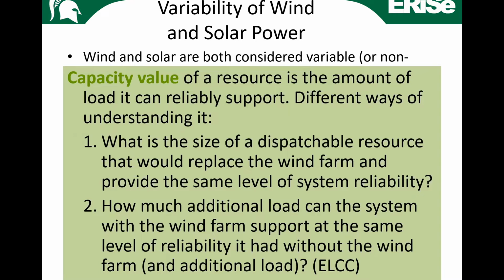And that's an important planning metric because capacity value depends on a lot of factors. What the location is, both geographically in terms of wind availability and consistency of wind. For example, offshore wind will give you more consistent wind speed, so the capacity value is higher. At the same time, the other location-related aspect is location with respect to the grid.